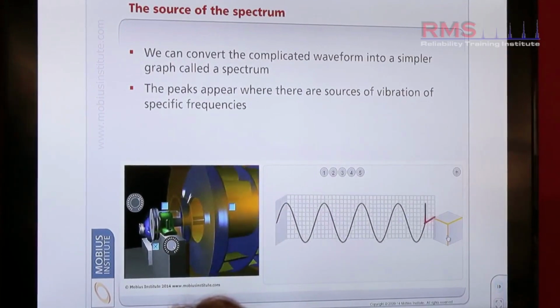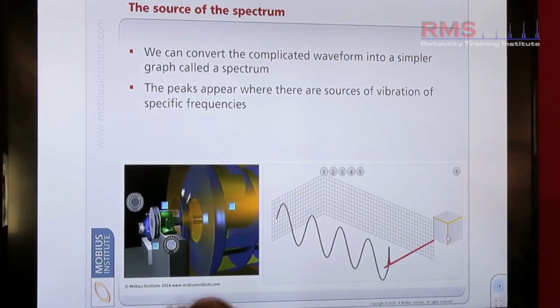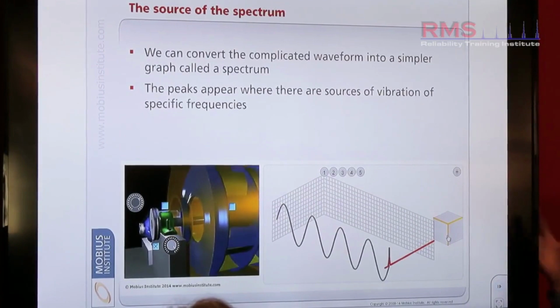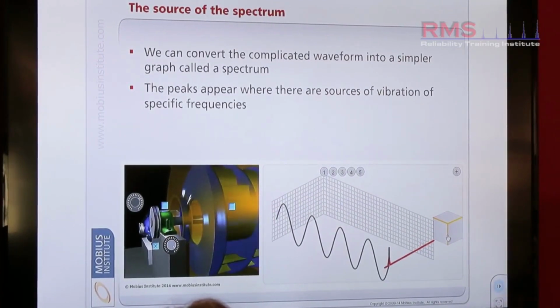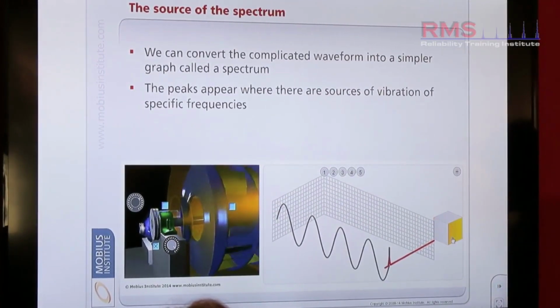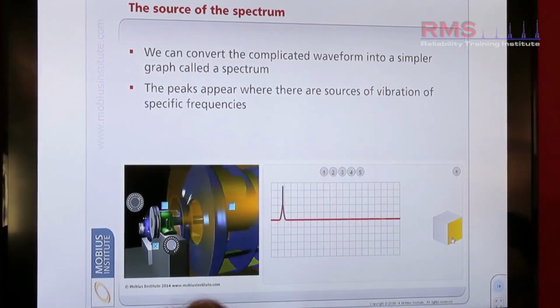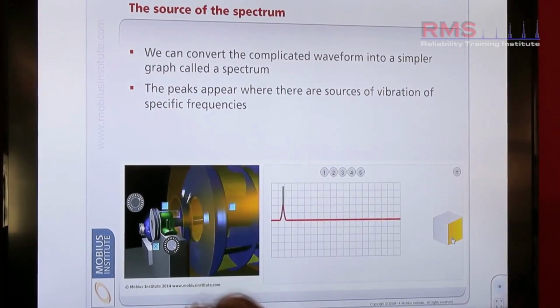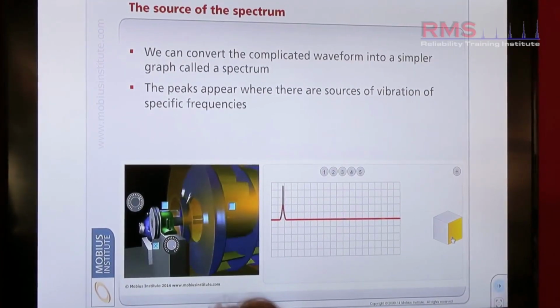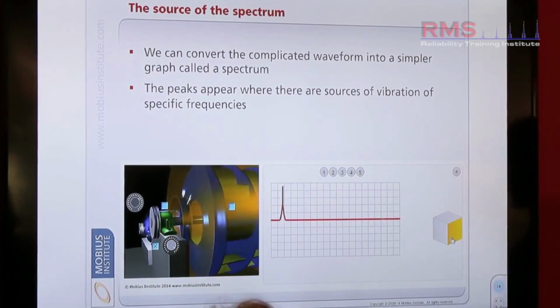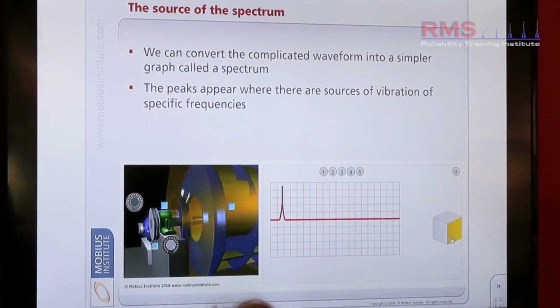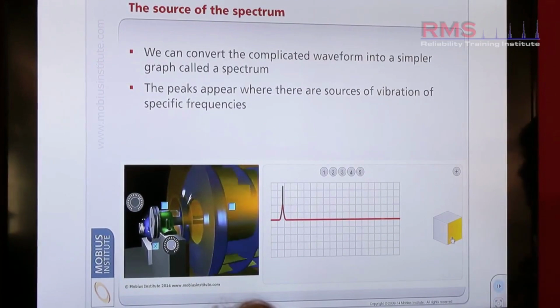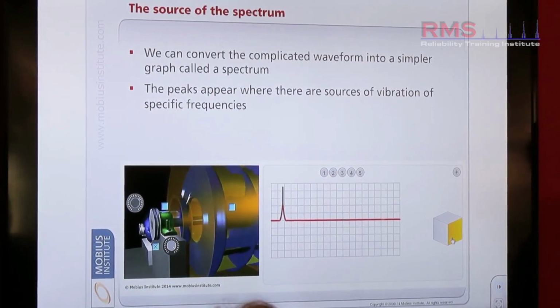So in simple terms, vibration systems today take the signal, initially like this, which is currently very simple, and they convert it to a frequency spectrum by initially turning that 45 degrees, and then if I complete the 90-degree rotation, what do we see? One single peak. What do I see looking at 90 degrees? I see the wave. So we take the time wave and we convert it to a frequency peak. Very crisp, very sharp way of presenting the data. This peak here would be proportional to rotational speed.